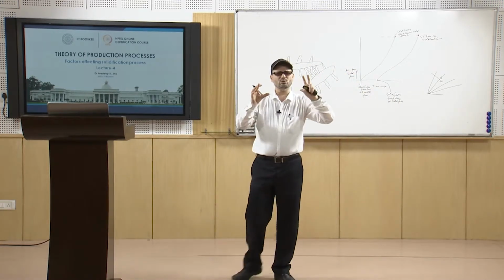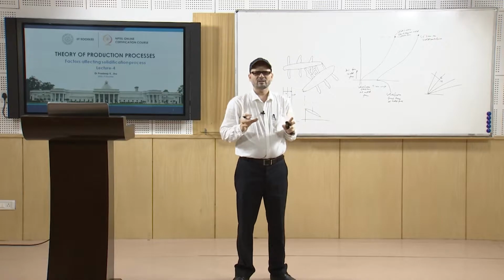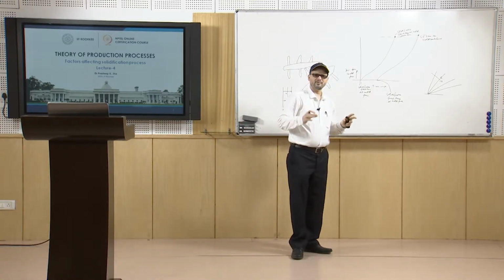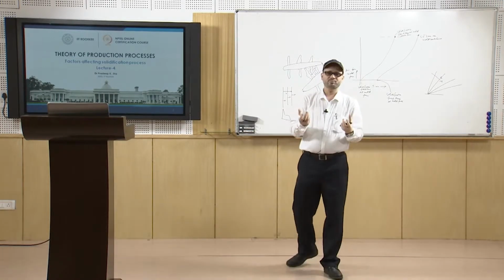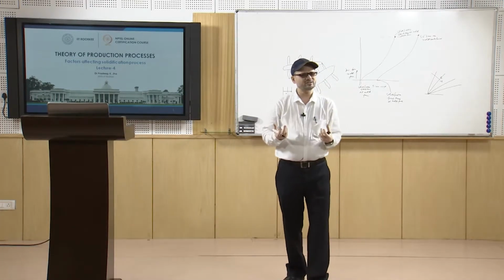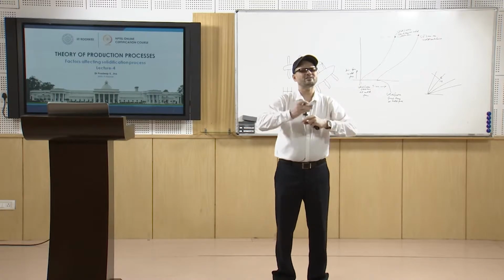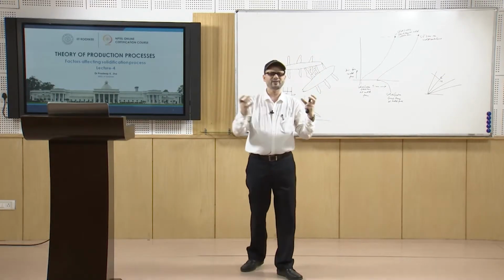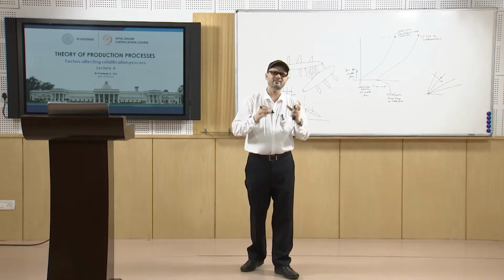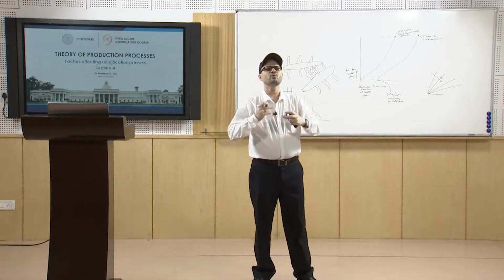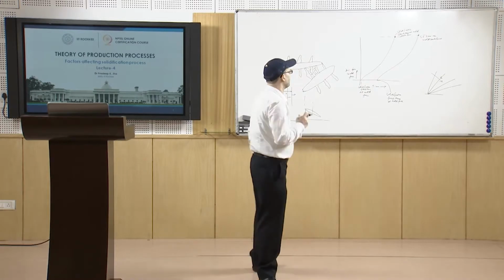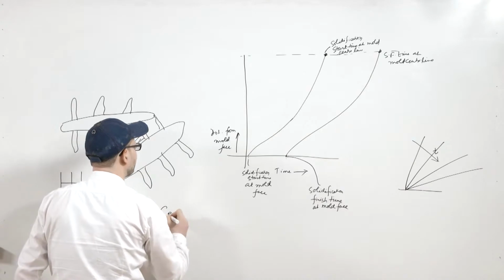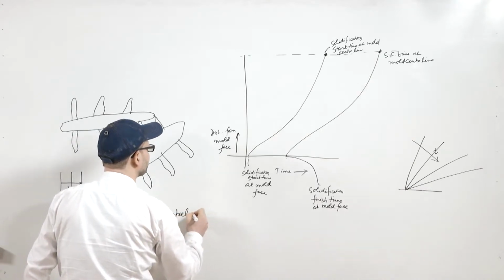As you go towards the center, there will be more and more resistance for feeding. It will be very difficult to get a clean, defect-free structure, because there are more chances of shrinkage defects, with liquid entrapped between the arms of the dendritic structure. So the parameter defined is known as center line feeding resistance.